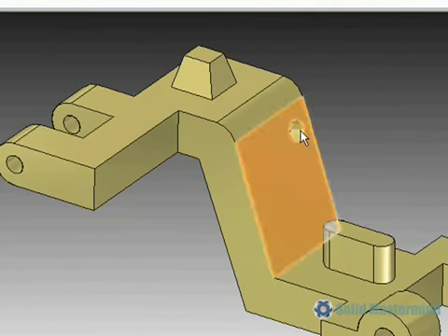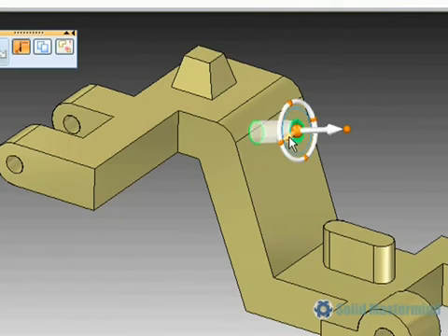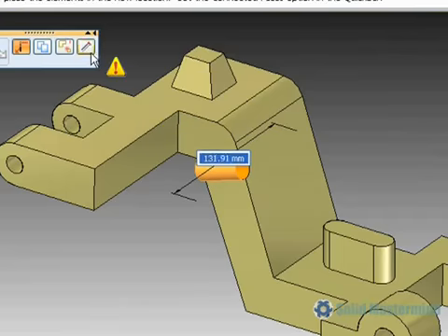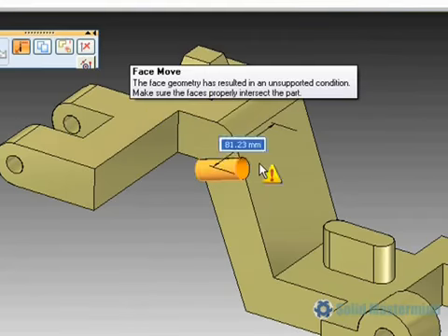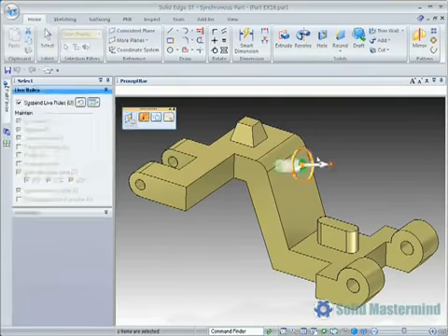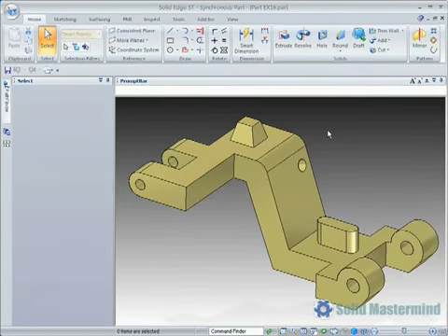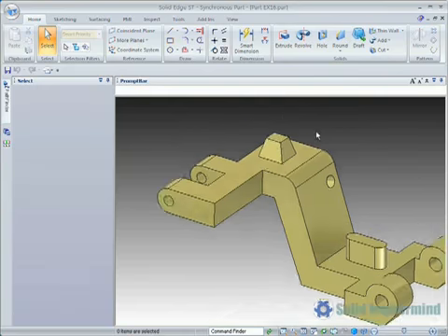Next, we'll select the hole and then the secondary axis to initiate the move. Also at this stage, we'll turn off the key point locate so we don't snap to any geometry. Hitting escape during a move will cancel the operation and the model will remain unchanged.